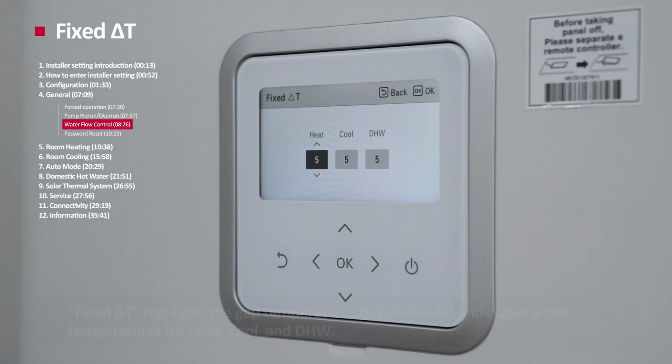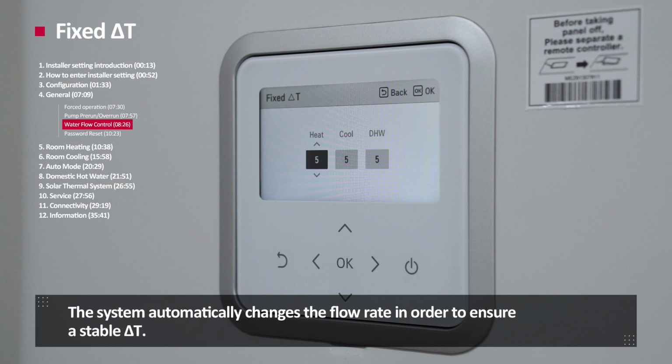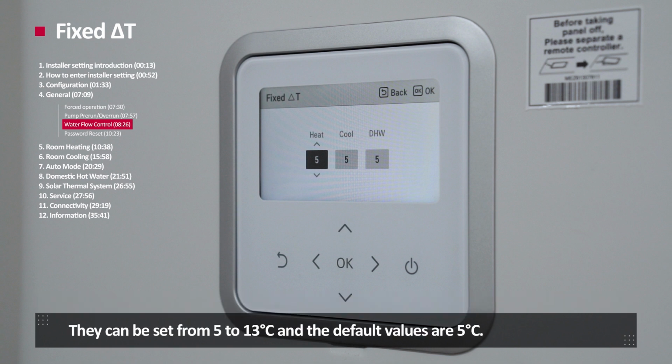Fixed delta T. Fixed delta T regulates the gap temperature between inlet and outlet water temperature for heat, cool, and DHW. The system automatically changes the flow rate in order to ensure a stable delta T. They can be set from 5 to 13 degrees Celsius, and the default values are 5 degrees Celsius.